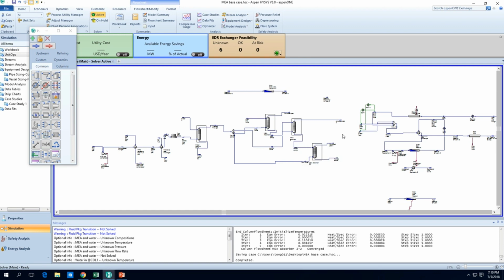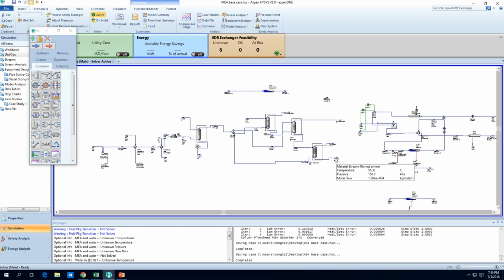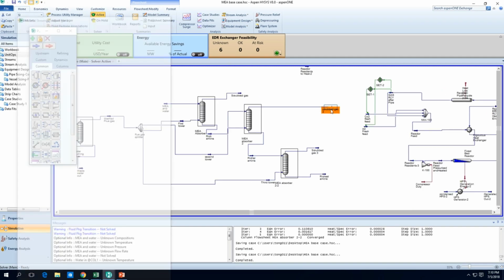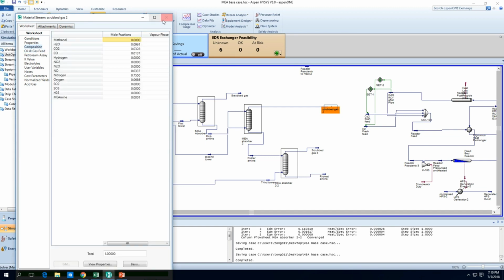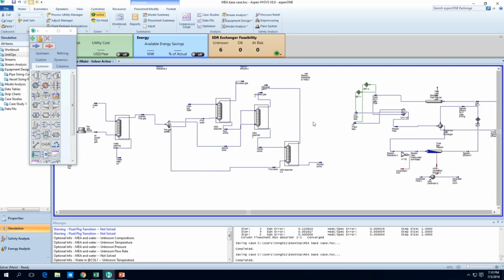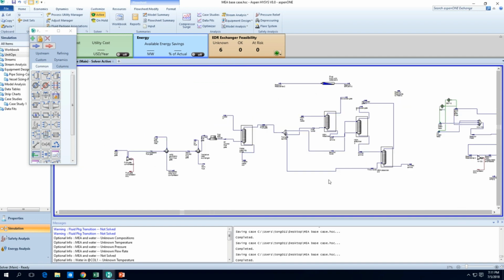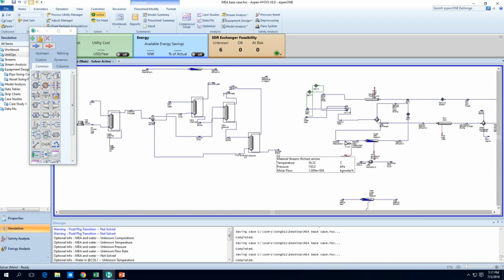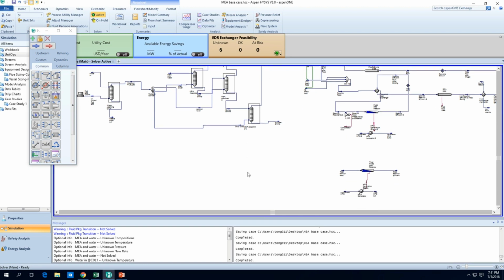Alright, so now this scrub flue gas is what we don't want. We don't need it anymore, so we're just going to leave it be. I'm just going to put it together on top here, so the 3 absorber towers. So we have this very rich amine, which we will now need to heat up in order to help strip the CO2 out of this amine. So we need to heat it up to about 117 degrees C.